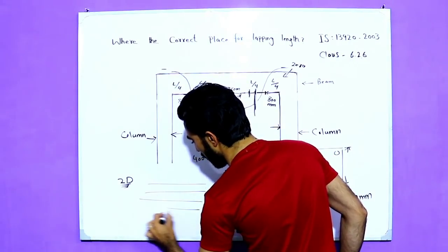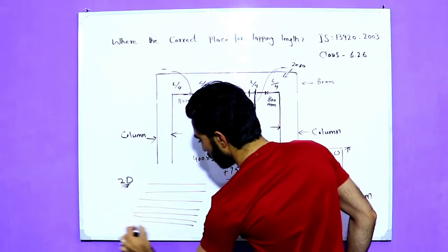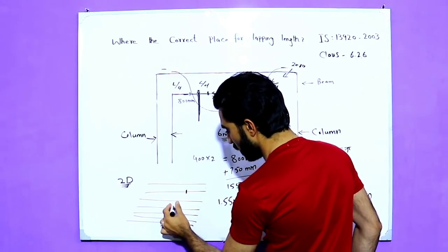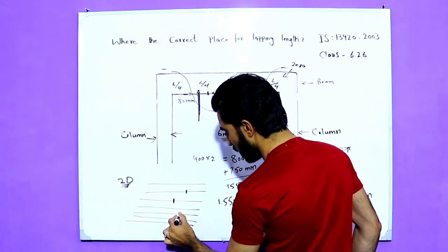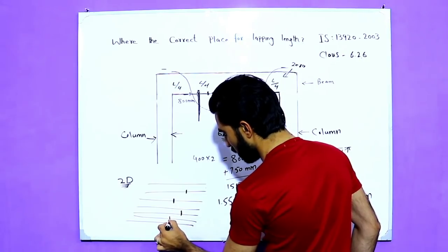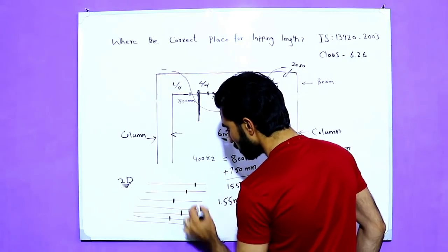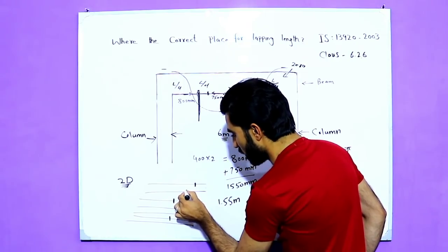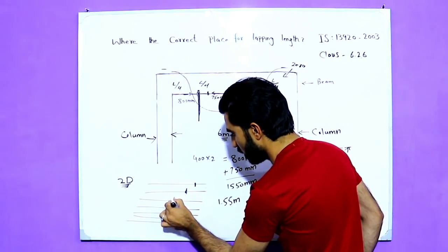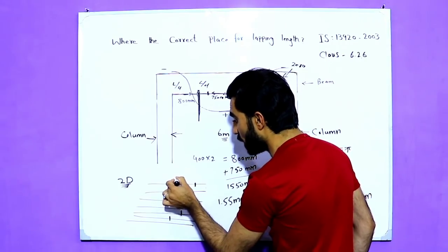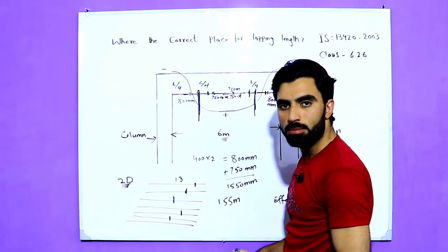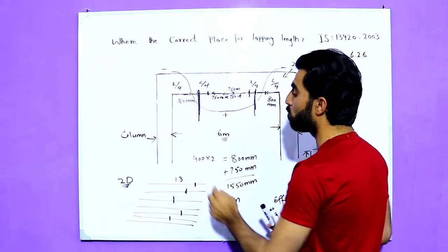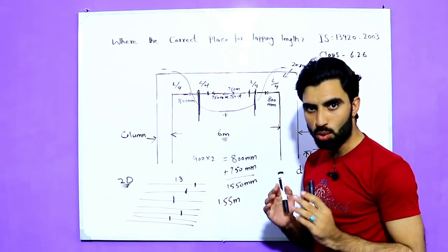For example, this is a slab. Okay, so here is lapping length, also here is lapping length, here is lapping length. Okay guys, they said from this lapping center to this lapping, the distance should not be less than 1.3 meter. So this should be the space.